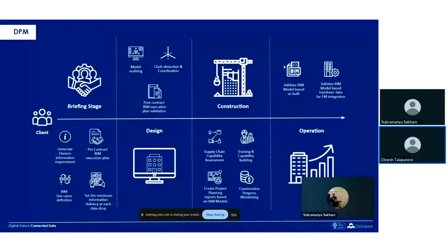So the as-built is progressively captured with laser scanners, and you update your 3D BIM model as per the actual site conditions and add all the non-geometrical information into it. This 3D model with all the information is helpful to take forward to operation and maintenance, where you use it as a digital twin. So that's the entire service of digital project management.